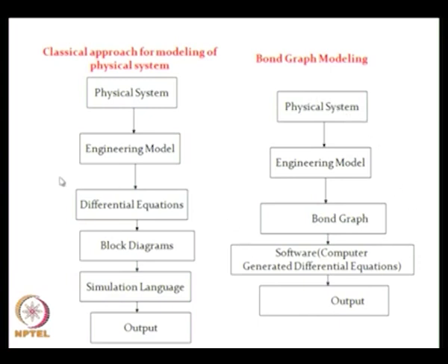We do not need to know the differential equations corresponding to the particular model, or worry about what kind of equations to be used and how to solve these equations. All these are done using the bond graph method. The only difficulty is that we need to know how to create the bond graph for this engineering model. No direct equations here, only the graphical representation.